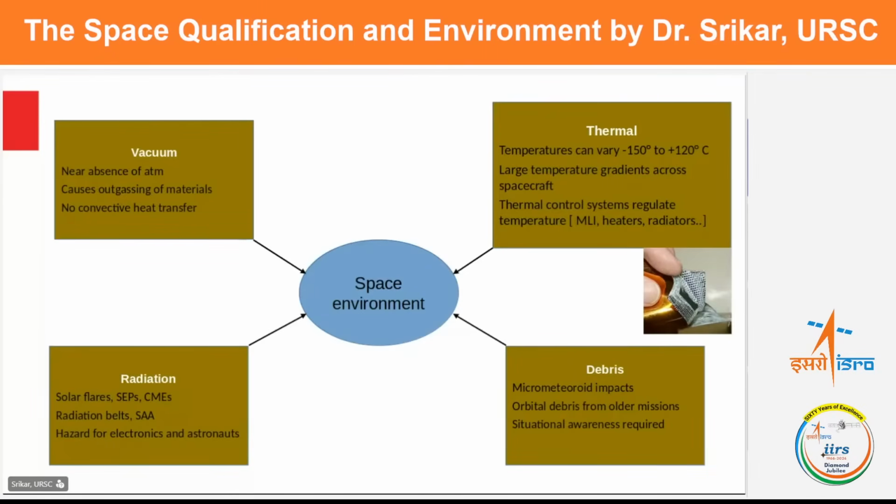So what is essentially done, and a very important thing that's done, is thermal control on the spacecraft and for each subsystem. We thermal engineers develop and employ different methods to regulate the temperature of each subsystem or each component in the way it is desired to be operated. And for that they use different kinds of engineering techniques. One of these, as I've shown you in the small picture, is this MLI, multi-layer insulation.